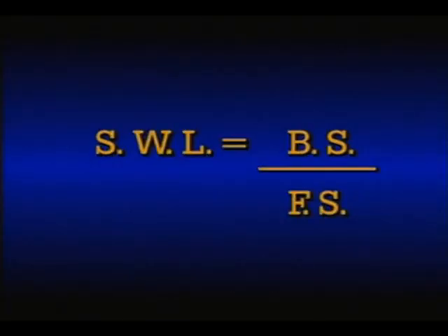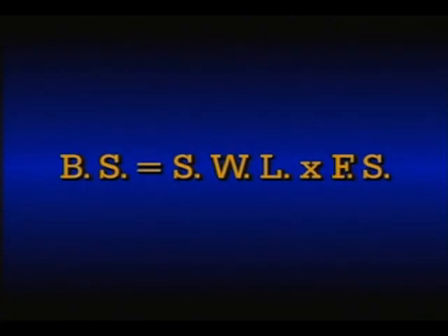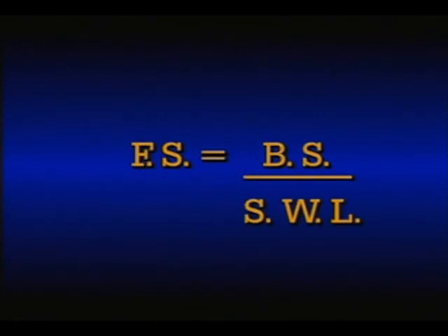Safe working load equals breaking strength divided by factor of safety. Breaking strength equals safe working load times factor of safety. Factor of safety equals breaking strength divided by safe working load.